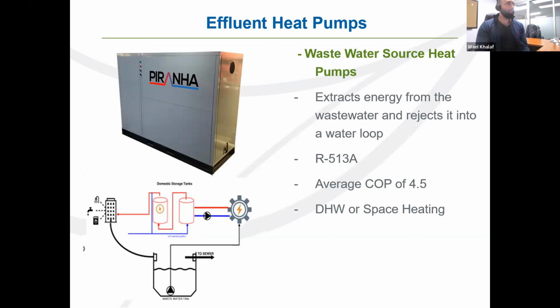just because the wastewater, or the effluent water, for a particular application in general has a decent warm temperature. If I look at an application with kitchen sinks, showers, toilets, a standard residential application, most of the time we're noticing that the average effluent temperature is around 70 degrees Fahrenheit. So if you go back to the original slides we looked at for COP, 70 degrees source temperature is a great temperature for achieving very high COPs if I'm trying to heat the water up to 120, 130, 140 degrees Fahrenheit.